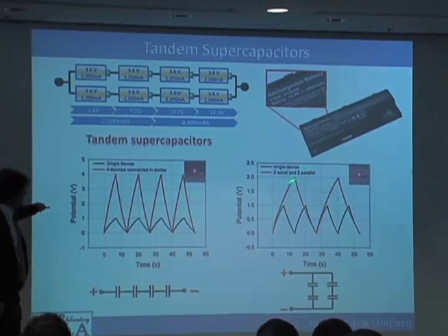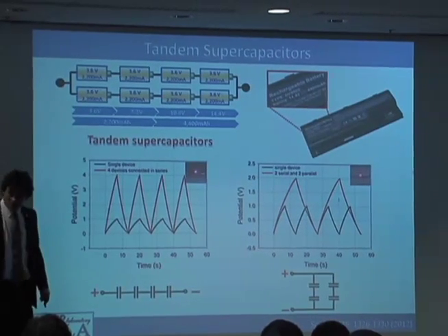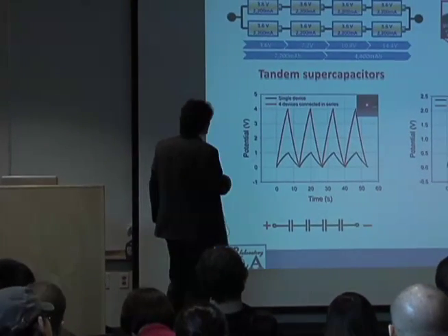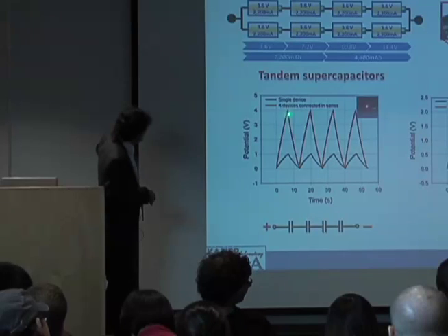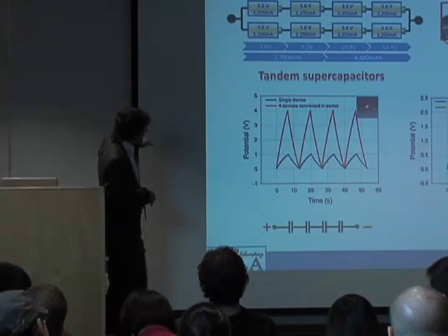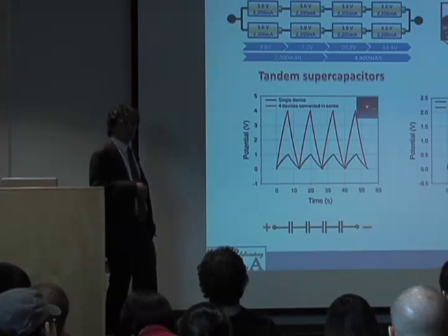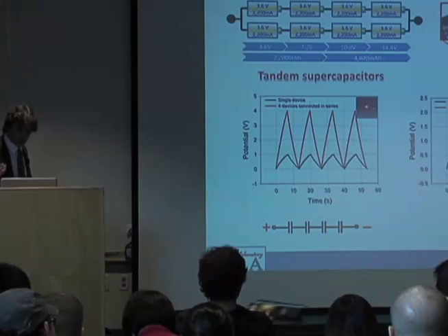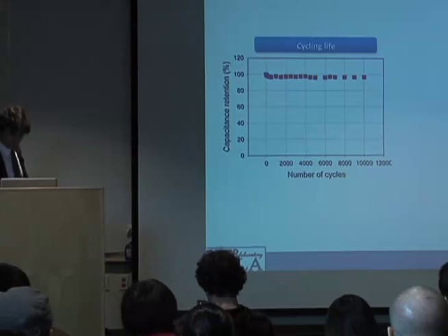And we double the area under the curve. So one of the things this tells you is the internal resistance of these cells is very, very low. In fact, if you look at charge-discharge curves, if there's an internal resistance, you get an IR drop right here. And it's very hard to see much of an IR drop. So we have very low internal resistance cells. So you can stack these and get whatever voltage you want. You can up the current.